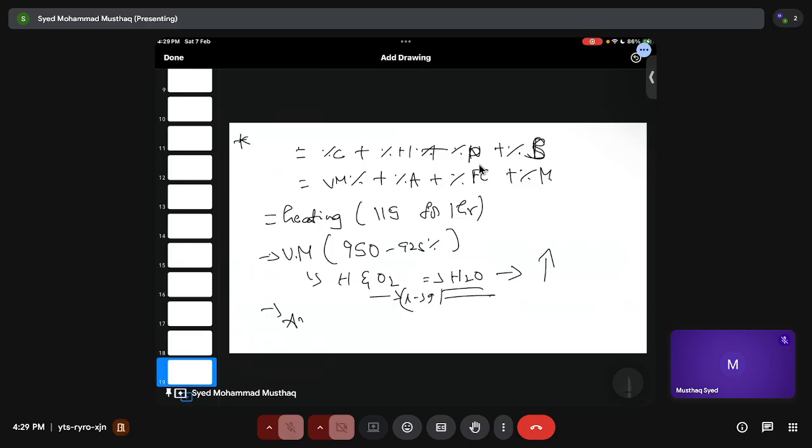And there is the ash percentage. Now ash percentage is defined by first heating your coal in air. Everything else happens in the absence of air, because otherwise your coal will get oxidized. Now to know the ash concentration, you heat it at 450 degrees centigrade for about 30 minutes. So all the sulfur and part of the carbon will get oxidized.